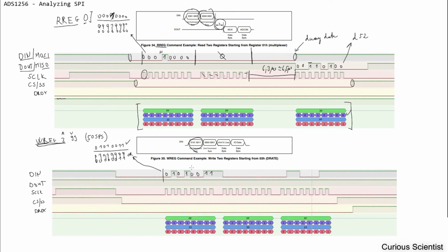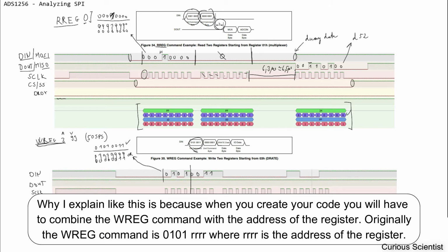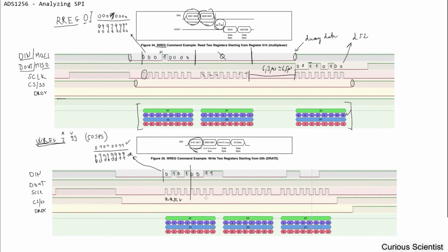So if you see this, then this is the write register part of the command, and this is basically the address part of the command. And then again we have a byte equivalent of zeros, because we neglect the second command byte. And here we don't need any delay. If you can see, there is no delay, as in this case, like T6.